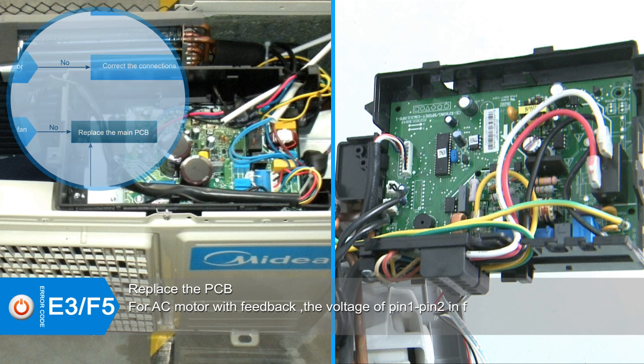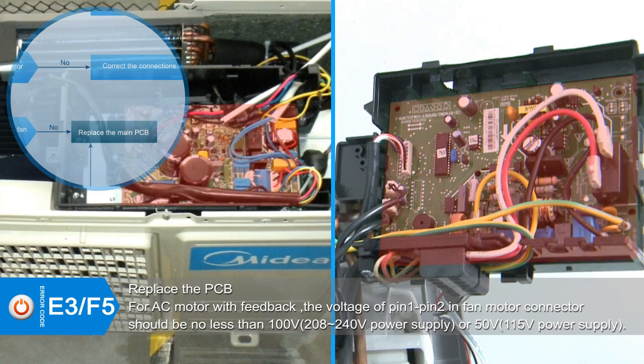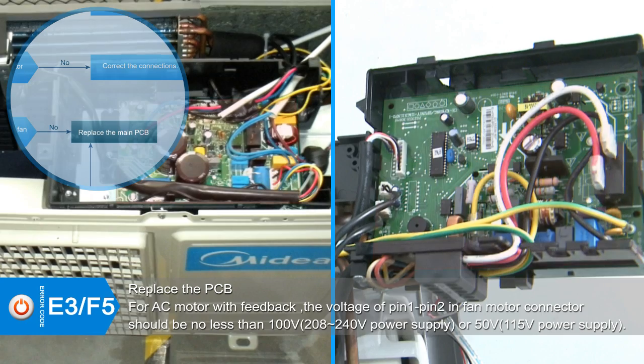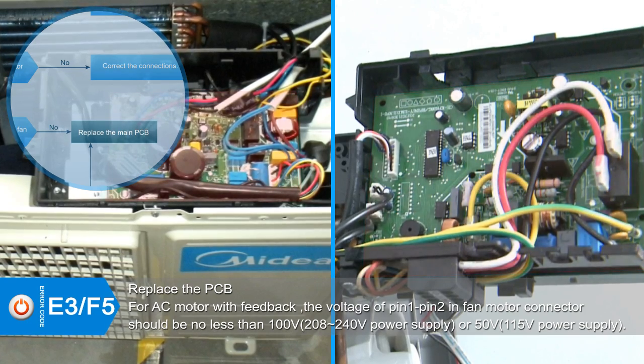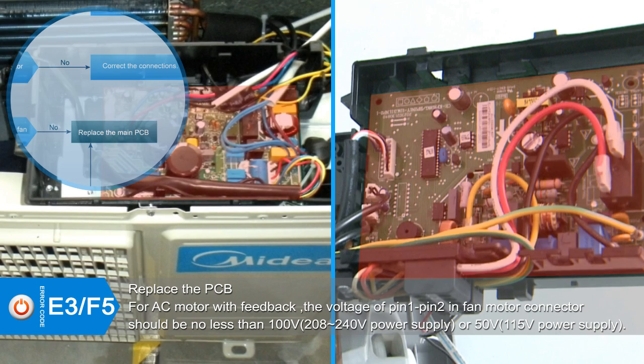Examination for main PCB board: AC motor with feedback. Turn the power on and set the unit as running in high-speed mode. 15 seconds later, measure the voltage of pin 1 to pin 2 in the fan motor connector. If the value of the voltage is lower than 100 volts for 208 to 240 volts power supply, or 50 volts for 115 volts power supply, the PCB must have problems and needs to be replaced.